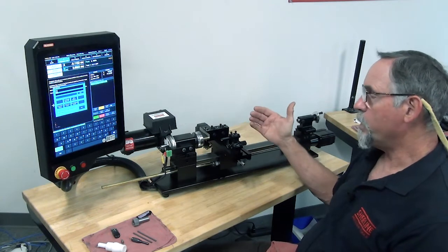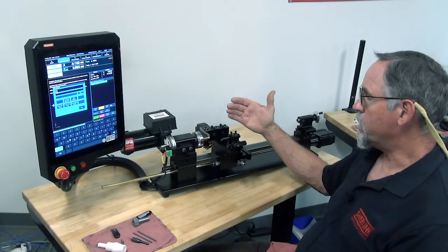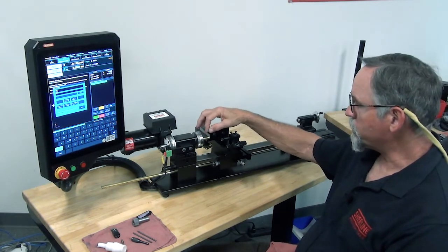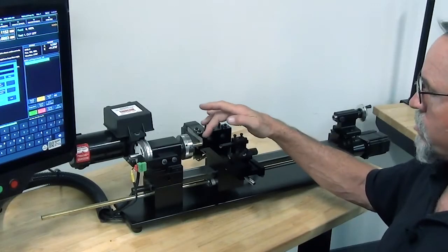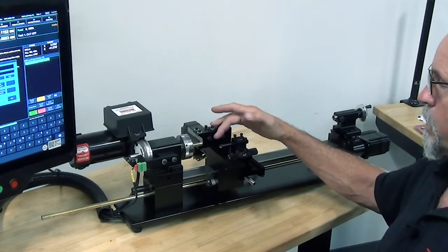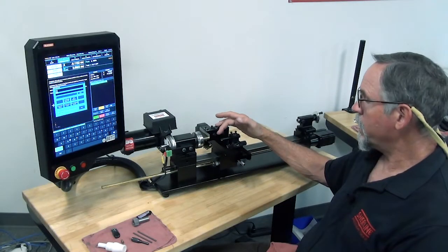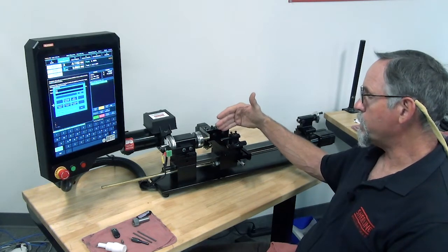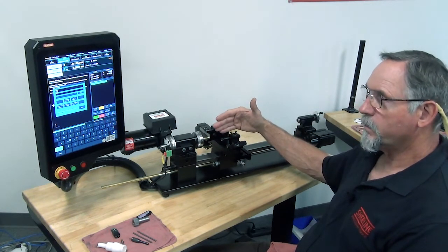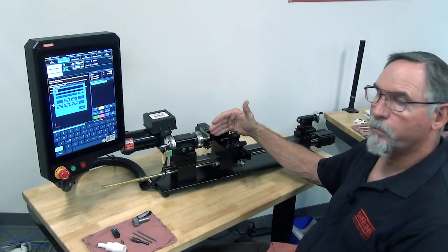Okay, so when you program it, when you get done, you have to know which tools are sticking out further and what their relationship is. So in the program, I would actually move this guy out to about 1 inch, Z plus 1 inch. Then my next move to this tool would always be an X move first to move it into position, and then bring it into the part.